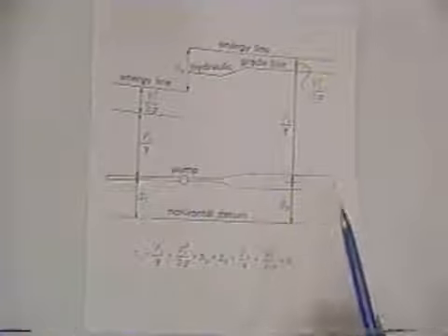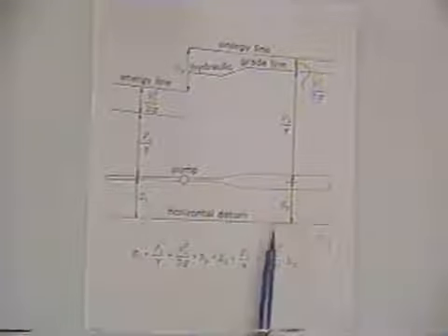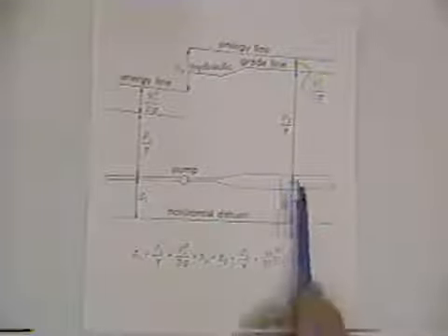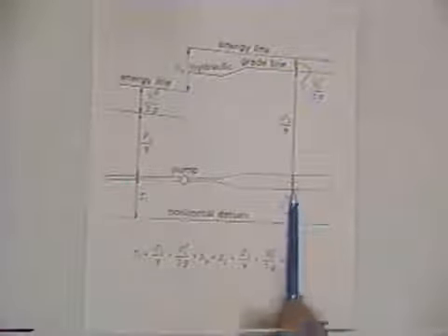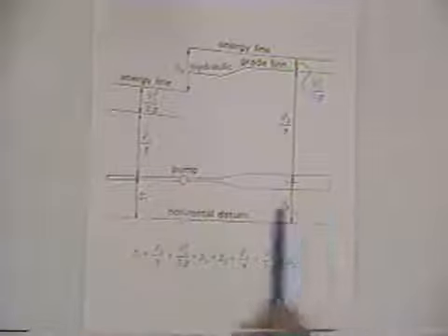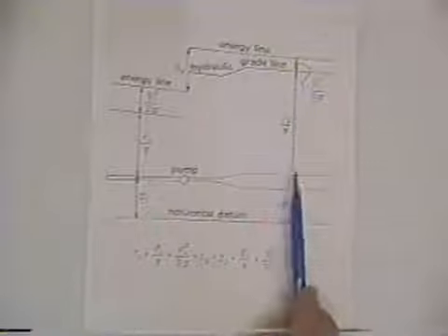If you change the velocity head, there's got to be a change someplace else. This is an accounting system. Whenever you add velocity head or subtract velocity head, it's got to come from either pressure head or elevation head. And so we can see in this case we made the diameter of the pipe larger as the water is flowing from left to right, and that decreased the velocity head, and so that came from pressure head.